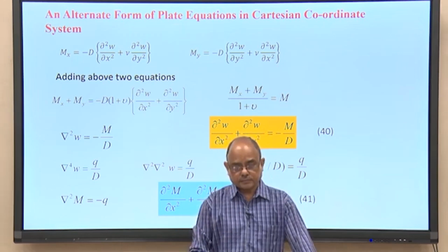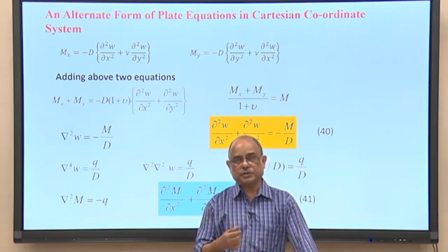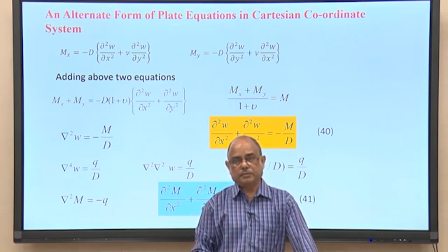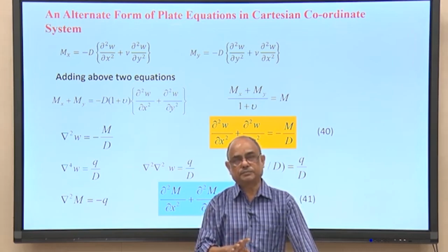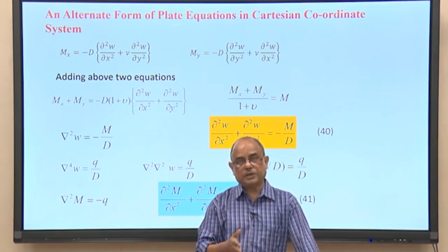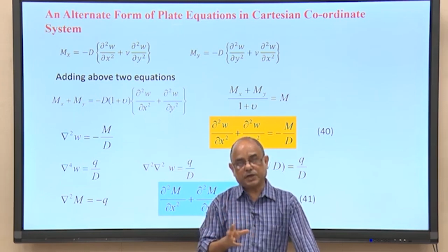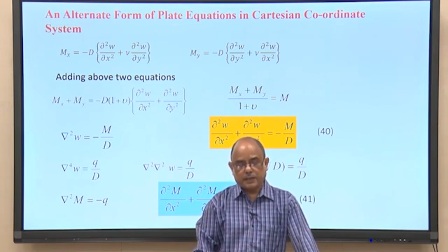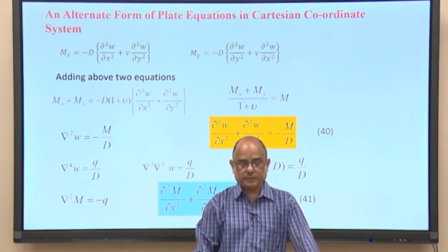Now, you can see that when you solve any differential equation and an exact solution is obtained, we need to satisfy the boundary condition. Because if the boundary condition is not satisfied, this will not be an exact solution. Therefore, the different boundary conditions in the plate have to be known, and based on the different boundary conditions, different methods of solution have evolved. In theory, generally in exact solution, no definite method is used.